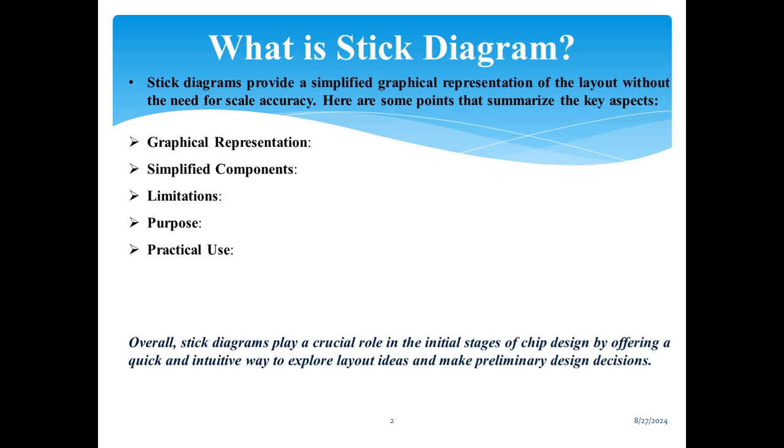Purpose. Despite their simplicity, stick diagrams serve as a useful tool for conceptual layout design. They provide guidance for initial layout planning, allowing designers to visualize the arrangement of components and connections. Practical use. Designers often use stick diagrams to explore different layout possibilities, adjust transistor placements, reroute wires, and optimize layout efficiency. They can be drawn using basic tools like colored pencils or dry erase markers, making them flexible for an iterative